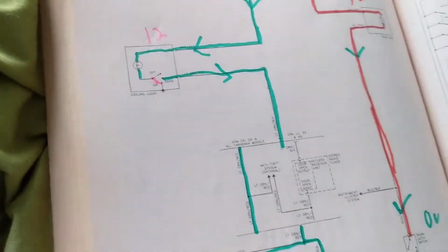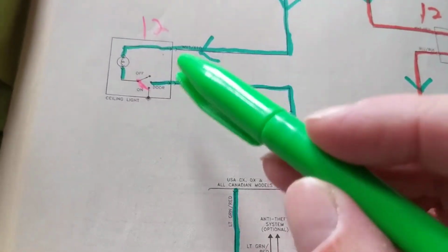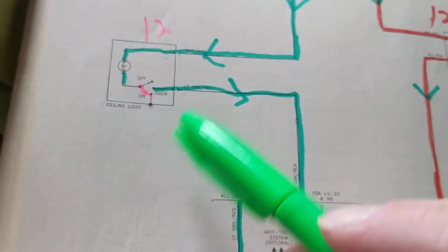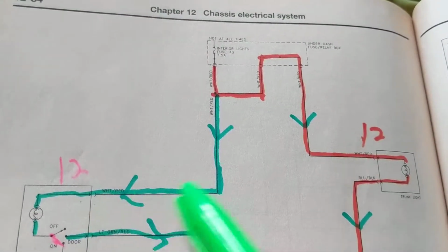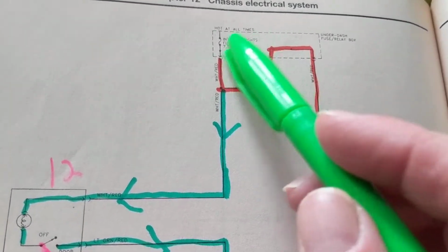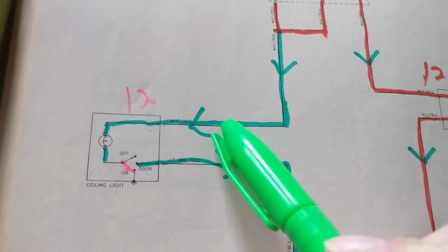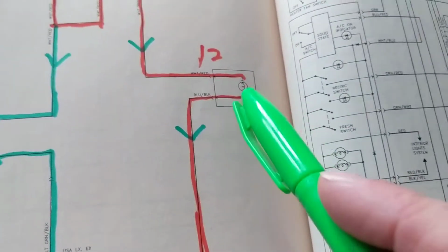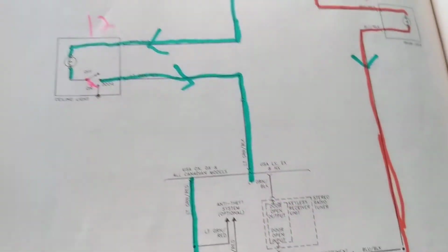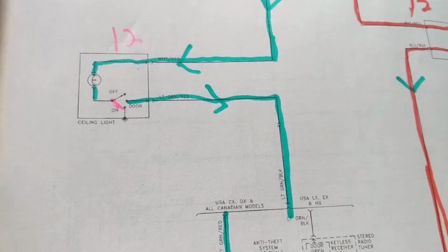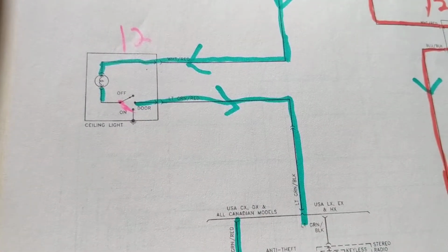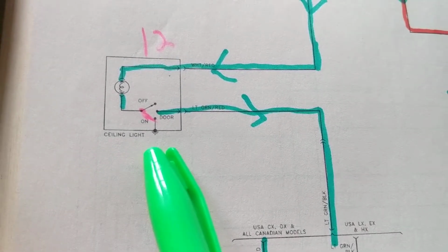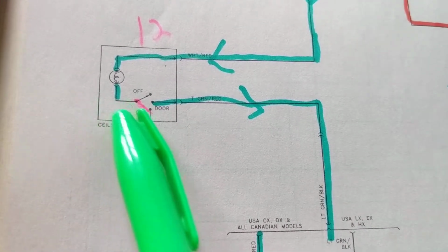0 volts. Now, for troubleshooting, if I come over here, one side of the bulb, and I measure 12 volts, that's good. What does it mean? That means I'm connected through the bulb to the battery. That's great. How much should I expect over here? Well, isn't it the same as this example? I'm connected to ground. So if this is connected to ground, it should be 0. But let's say I don't measure 0. Let's say I want to put the ceiling light on. That means I have to activate the switch in this position.